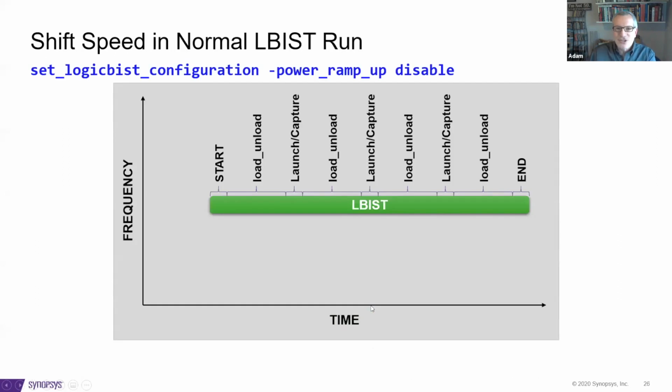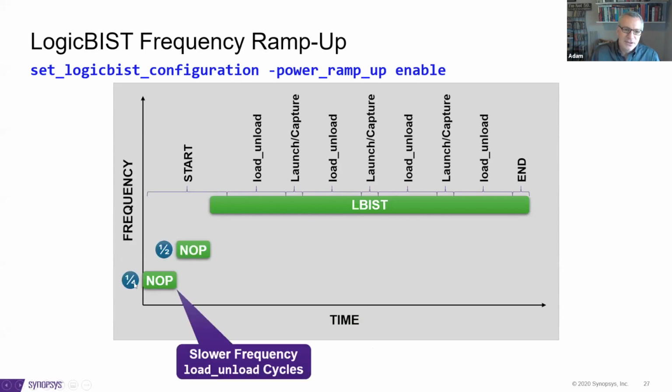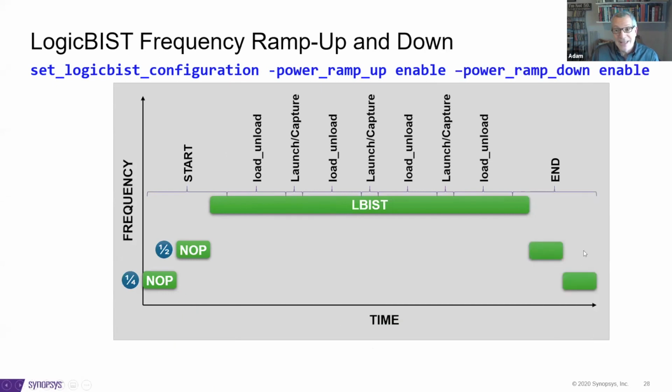So leveraging that same issue, and again, this is something that Dave was mentioning as well, for logic BIST, you want to start slowly from a shift standpoint and end slowly, slowing down as well, so you don't get this big spike in current need, and therefore a big IR drop, which can't be satisfied, for example, in an automobile with the wimpy wiring and poor power distribution circuitry.